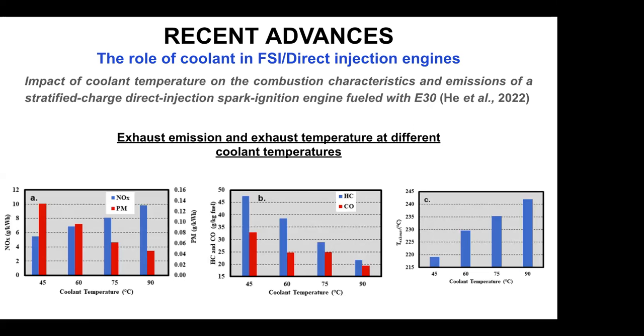The higher exhaust temperature would allow the after-treatment system to heat up more quickly, thus ensuring a more rapid light-off of an oxidation catalyst, for example. Okay, next.